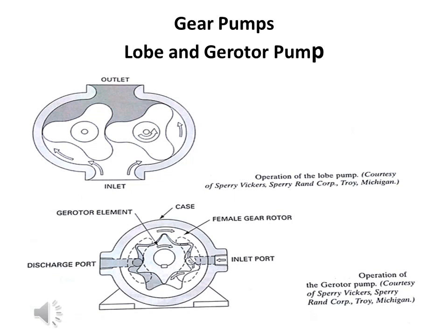Now as seen in the drawing, one lobe is always in contact with the other lobe, and in between the lobes there will be an oil film. The lobes will also touch the outer casing, and between the lobes and the outer casing there will be an oil film as well. It is similar to the external gear pump.